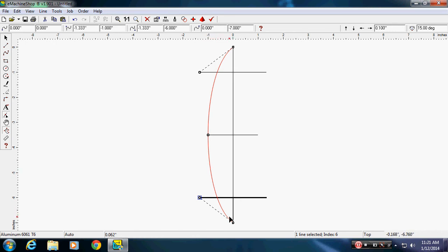And if you actually need just a round shape, then obviously you would just drop a radius in way out here and do it. But this is not a radius. This is an actual ellipse. So one of the things to remember, if you draw something like this in your CAD drawing, these are splines and not arcs. So in a DXF format going into a CAM program, it won't recognize this line.